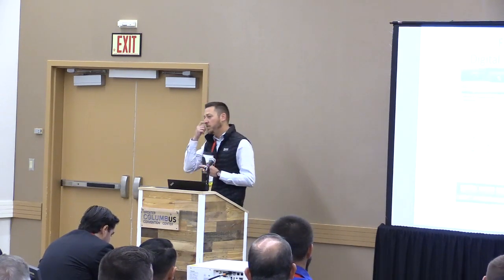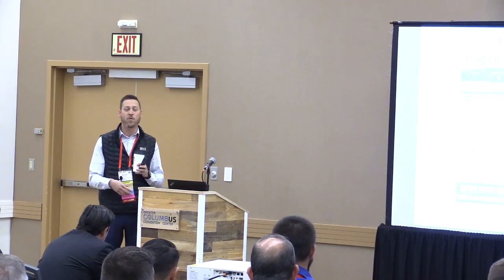So I can't tell you how often we go into a company and they've tuned their furnace for a temperature uniformity survey, and let's say they do have rheostats, and you go look at the rheostats and not one of them is set at 100%. You've got one at 90, you've got one at 82, you've got one at 78 or something like that, right?